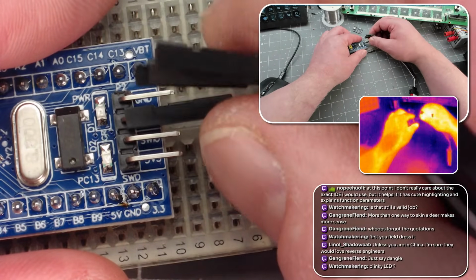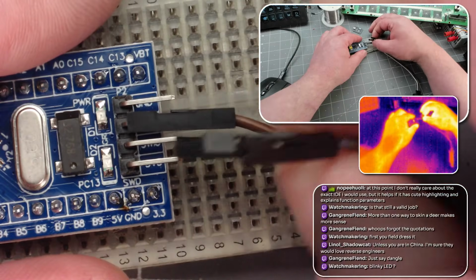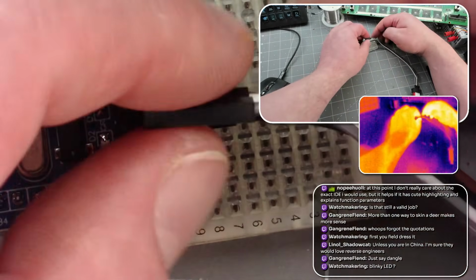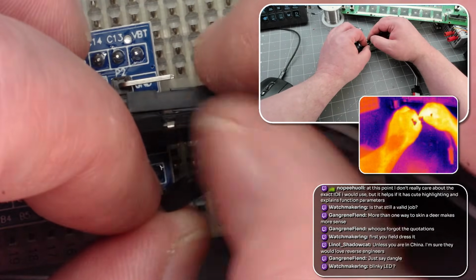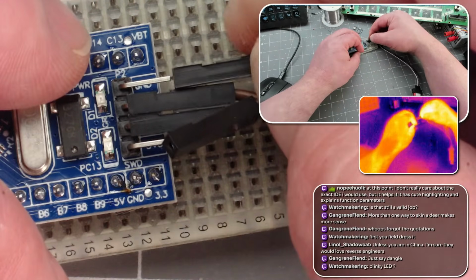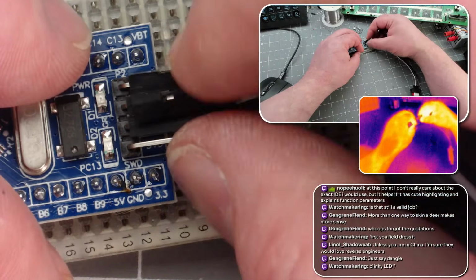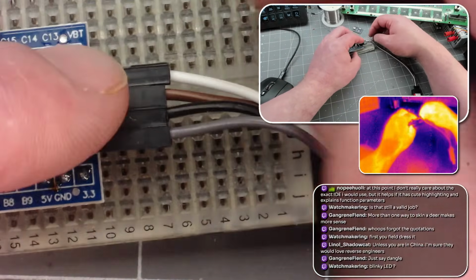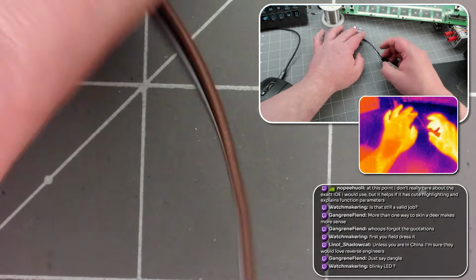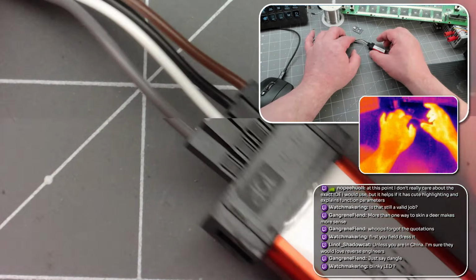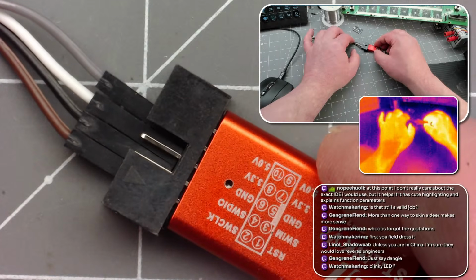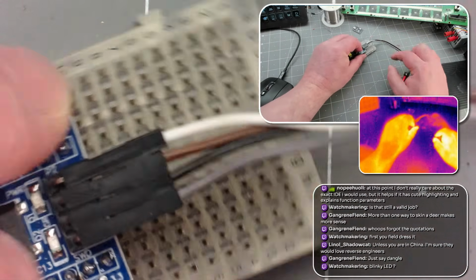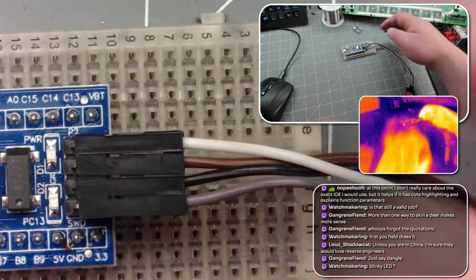The reason that I'm talking to myself like this when I do these things is because I've gotten it wrong enough and blown up enough microcontrollers that I feel it is necessary to repeat all these things, do the silly thing, but also check, double check, and redouble check everything. So my ground pin is definitely going to ground, right? Yes. And the 3-volt pin is on gray. That's definitely going to 3-volt. Yes. Okay, so technically we are connected to this thing.